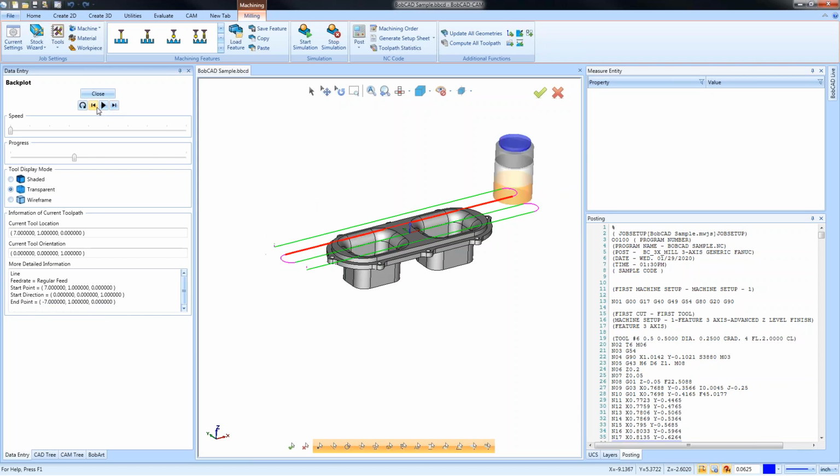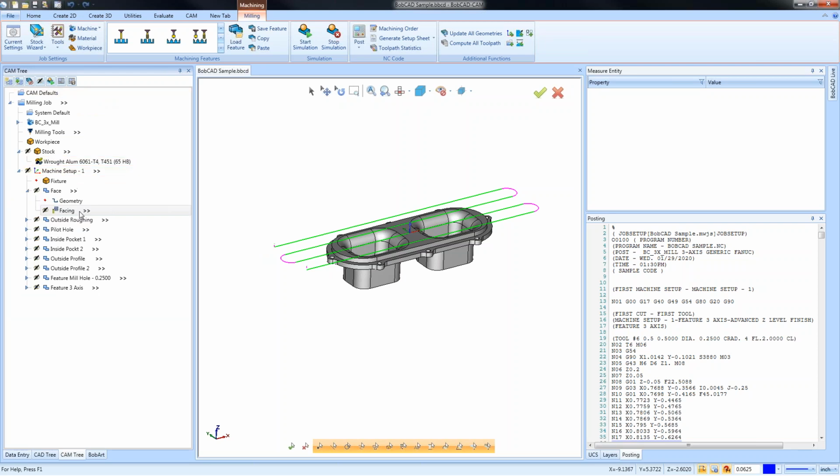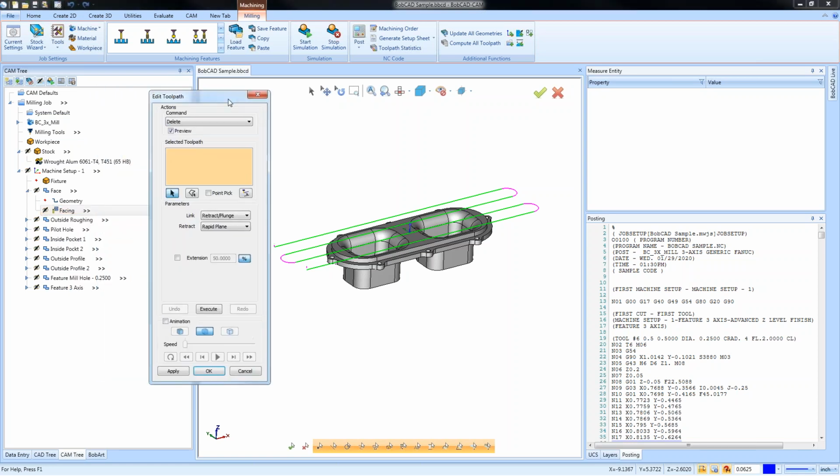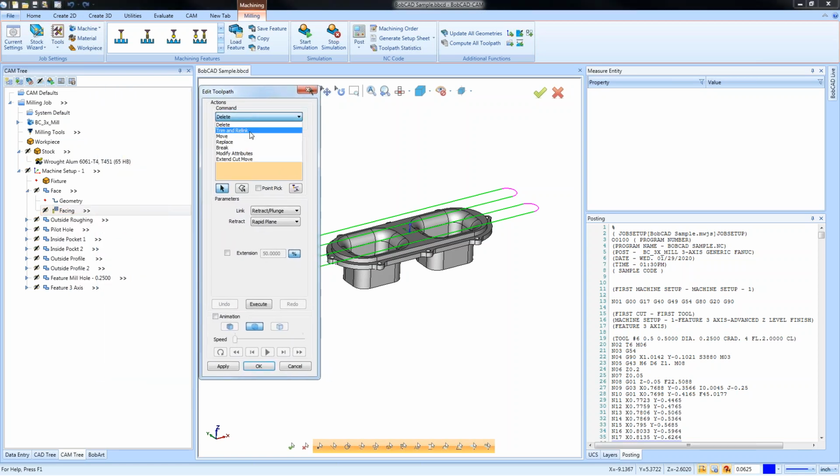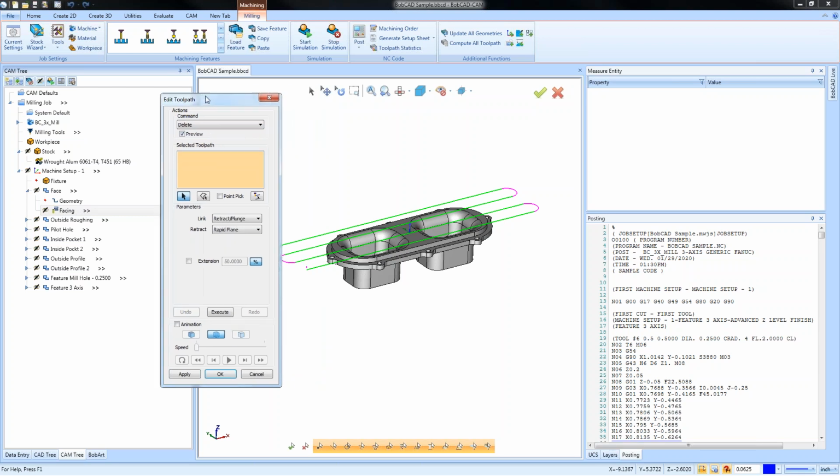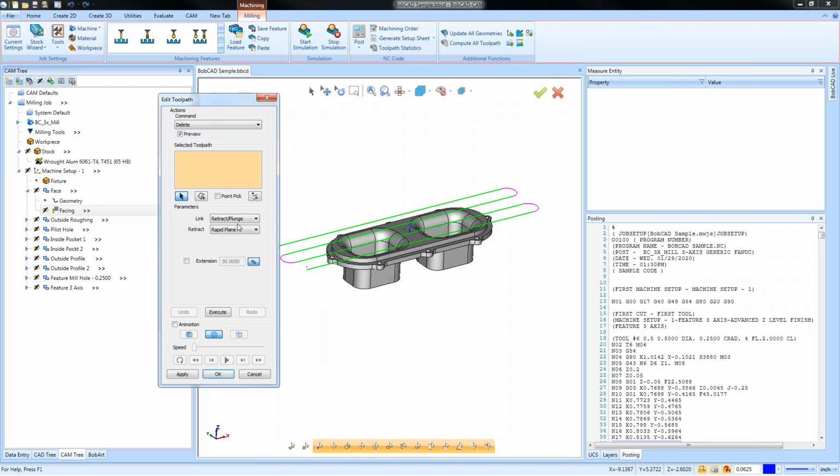So not only is this helpful for where the tool starts and where the tool ends, it's also very helpful for what feed rate mode it might be in at that time. Okay, and again, even though this video is not about the toolpath editor, we do have a toolpath editor in here. Within this editor, you do have a variety of different ways that you could directly edit the code. This solves the scenario of, you know, you got 90% of your toolpath dialed in perfect, but there's just 10% that you need to trim off or change or modify.